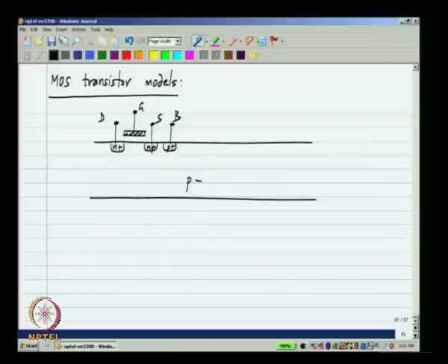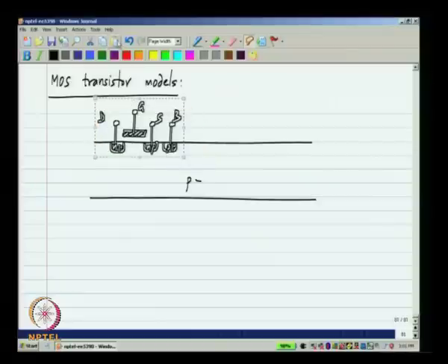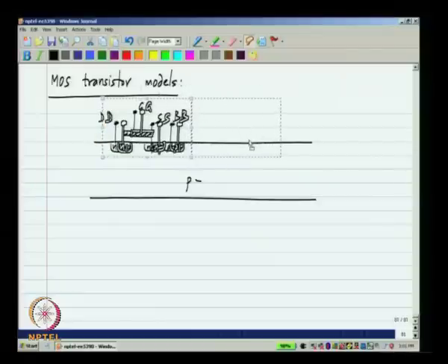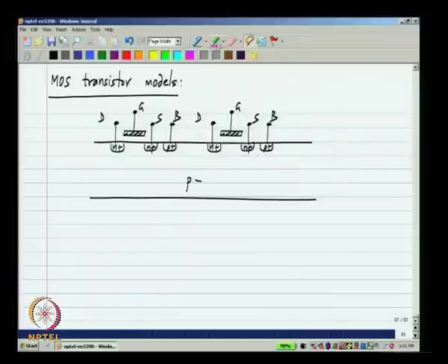Now, if you have two NMOS transistors, you can see that the bulk is common to both of them, and we need to keep all of the bulk source and bulk drain junctions reverse biased, because these drain and source junctions are there only to make connection to the channel that will be formed between them. These PN junctions should not be forward biased.